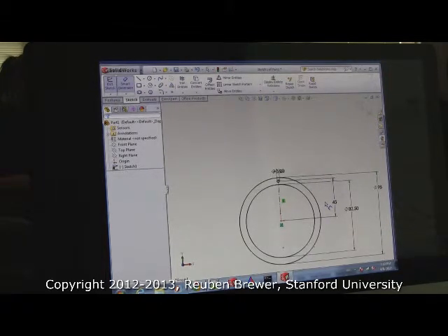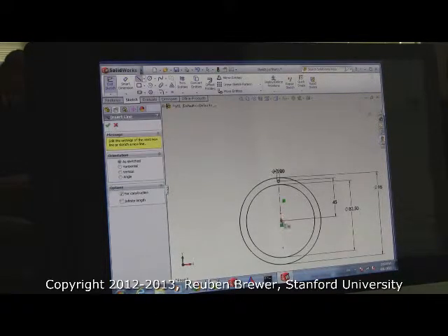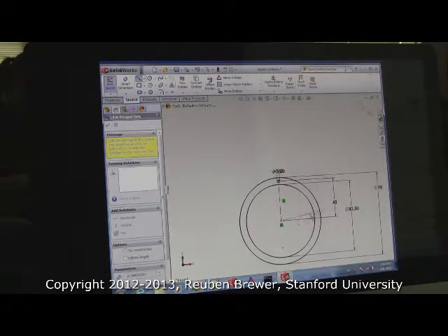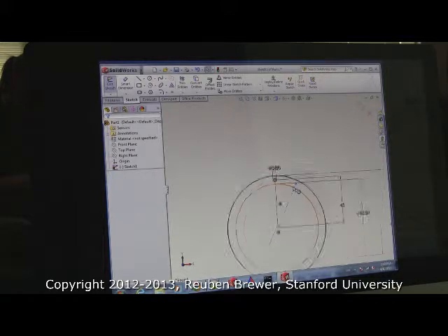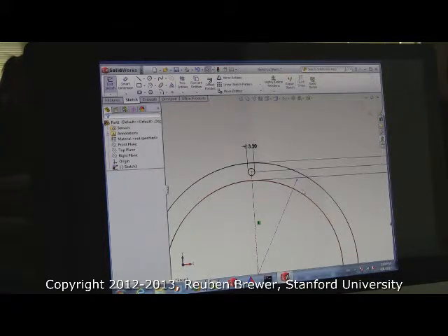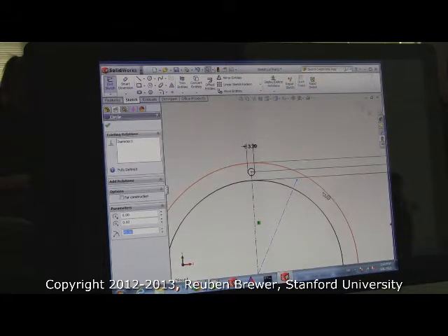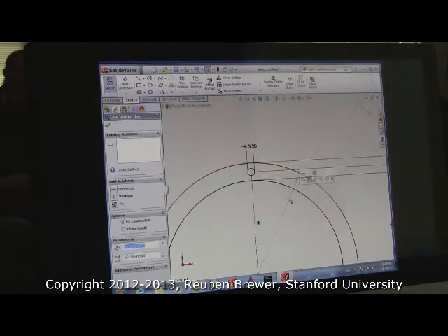Okay? Now we're going to do a second line. Go to the line, drag a center line, put one end in the center, and put the other around 30 degrees on that same radius. See here? Sorry, my line is black. If you select the wrong line, that's okay. In fact, I will delete that and do it.